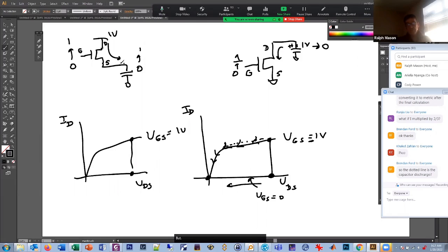Now, instead of discharging it, it's starting to charge towards 1 volt. But as we charge up here, notice this source voltage is changing. So VGS changes in this situation. Over here, we always had the same VGS, so we just stayed on this curve. But now as the source increases, the gate to source voltage, this voltage across here, is decreasing, right? This is at 1 volt, but now as we charge this up, instead of staying on this one curve, we're actually going to move to different curves. So the drain source voltage is going to go down, so we're still going this direction, but we're also jumping to a new curve. So we're going to go to this point next.